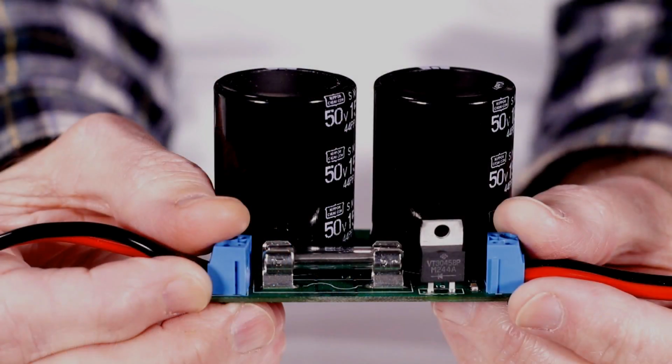Now that we know the why, let's talk about how we can solve this problem without having to drop the output power of the transmitter in the dirt. This is where this little circuit board comes into play. It is nothing more than 30,000 microfarads of capacitance with a blocking diode and a fuse. The blocking diode isolates the capacitors from the battery so as not to backfeed the battery. Let's take a look at the schematic.